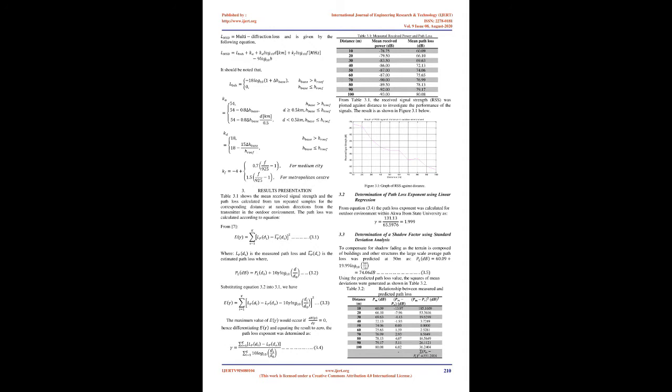It is necessary to adopt an adaptive deployment design methodology, known as infrastructure mode. In this mode, predictive deployment and network calculations are done using an accurate path loss model. There are several models which can be used for predictions in the outdoor environment. Such models are grouped into 3 major types: empirical models, semi-deterministic models, and deterministic models. We will briefly discuss some empirical models here.